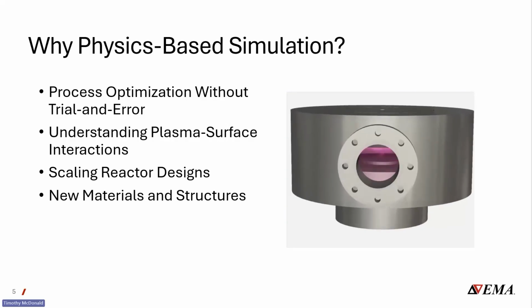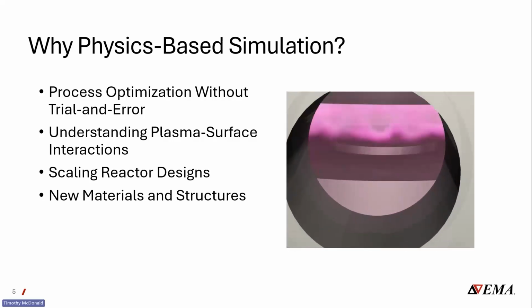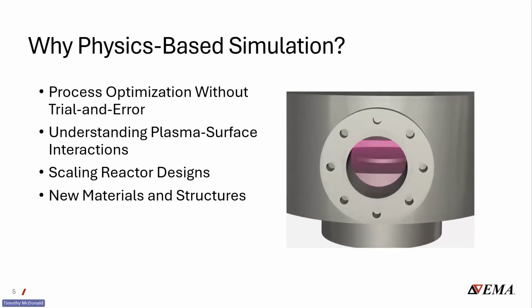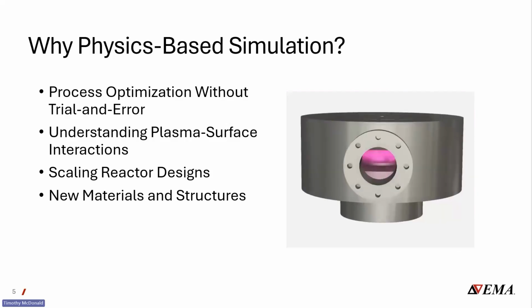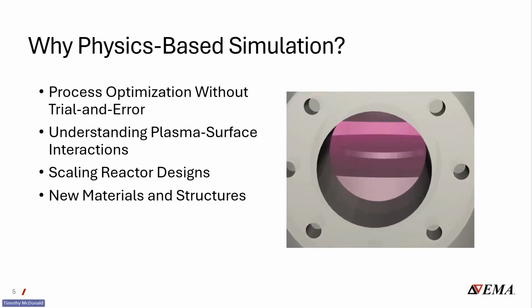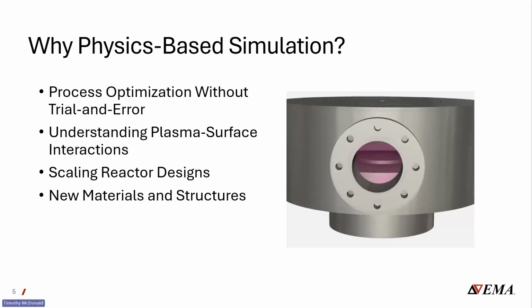And then the next consideration is scaling reactor designs. Next-gen PECVD tools must deposit uniformly across large wafers, 300 millimeters moving toward 450 millimeters. Simulation helps predict how chamber design, such as the shower head, pumping ports, and electrode spacing, affects uniformity across such scales.